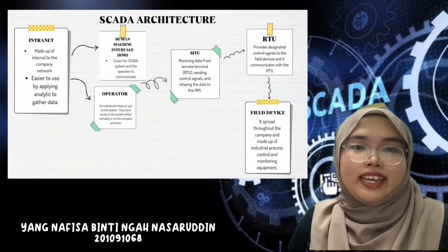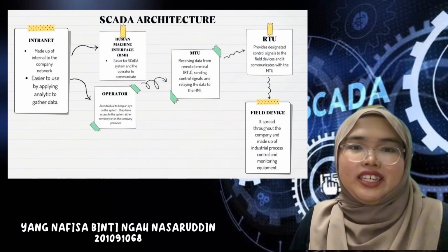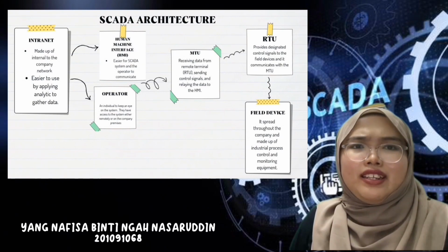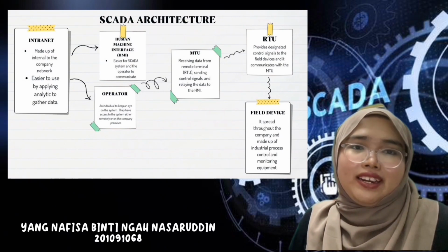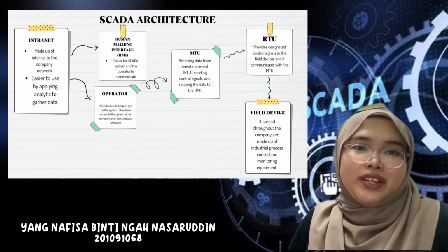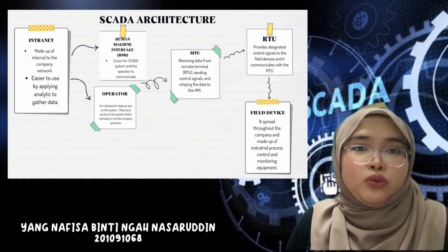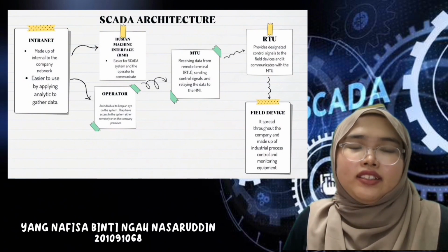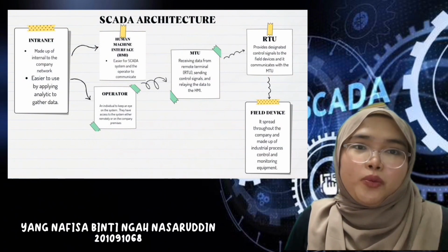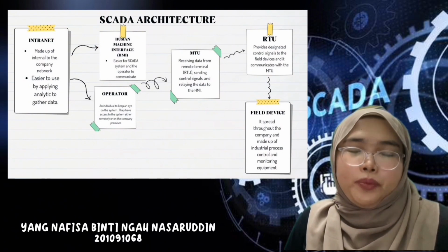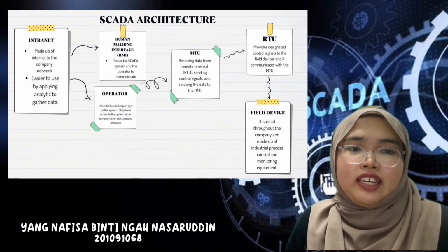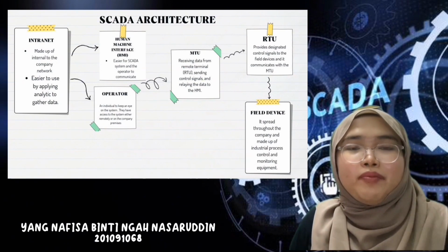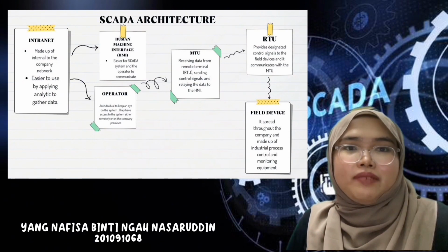We go for the SCADA architecture. Start with the intranet that is made up of the internal company network, and it is easier to use by applying analytics to gather the data. From the intranet, it will divide into two, which are the HMI and operator. HMI makes it easier for the SCADA system to communicate with the operator, and the operator is an individual that keeps an eye on the system, and they have access to the system either remotely or on the company premises.